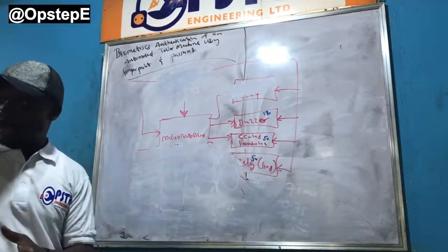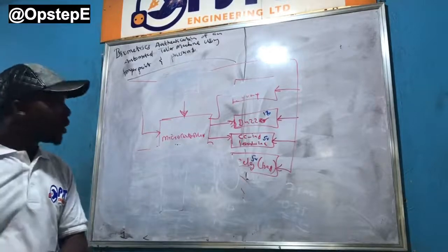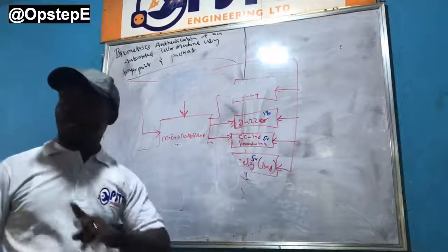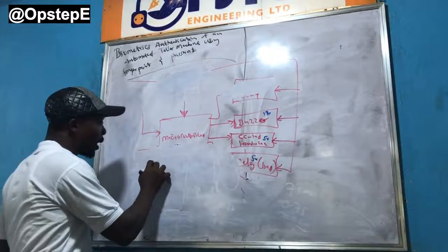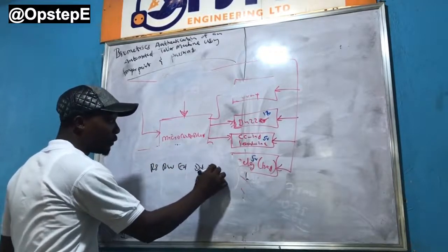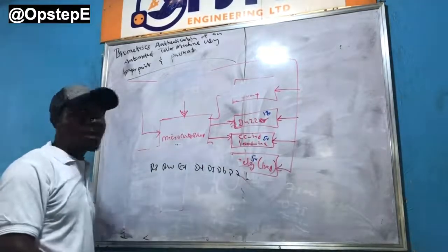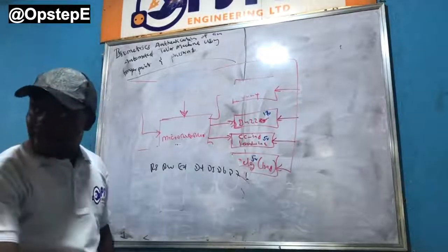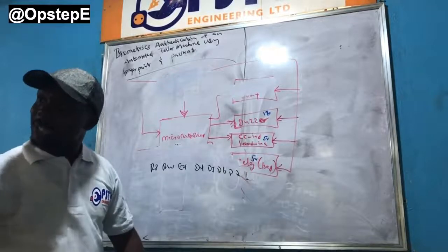On my port C is where my UART module is. So I figured, if my keypad or my SSD requires 8 pins, is it 8 or 7? 7. We're talking RS, RW, EN, then D4, D5, D6, and D7: 1, 2, 3, 4, 5, 6, 7 pins. I can't get 7 pins from port C because port C is 8 pins, and I need to take out transmit and receive from it.